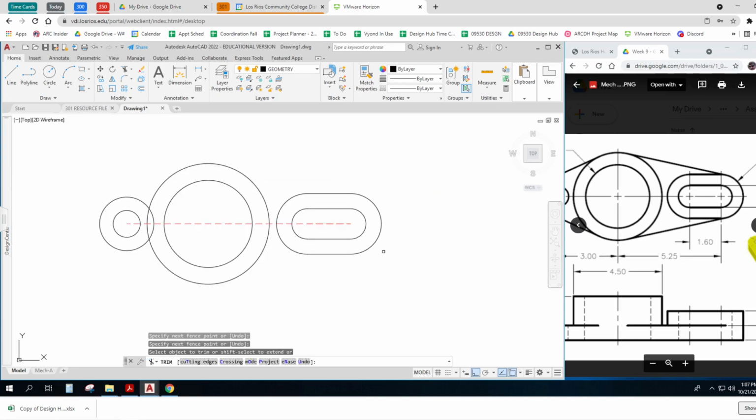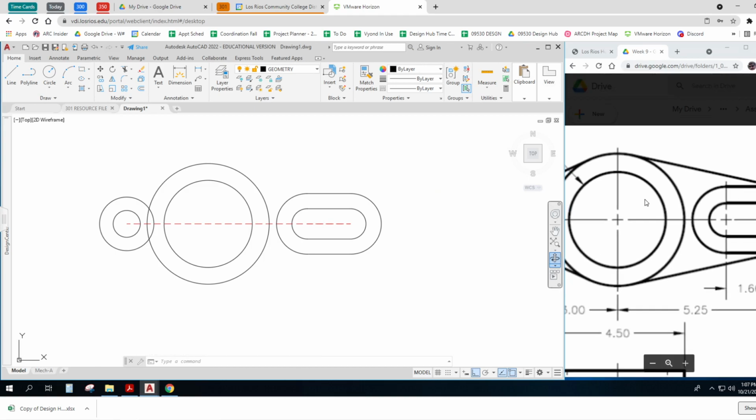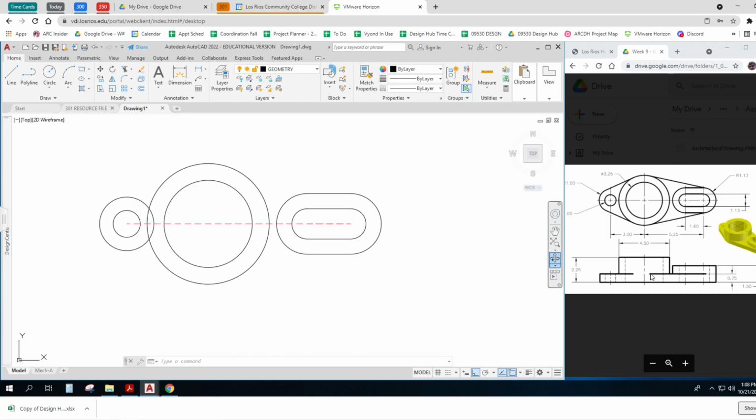That looks like it. That is so cool. Now I've got the one tricky part. It's hard to tell where this hits. But if I look at the one down here, this line right here is this line. See, it's that line right there when I look at it in the front view. And it does not reach the quadrant, and it goes past the quadrant here. So it must meet at what's called a tangent.